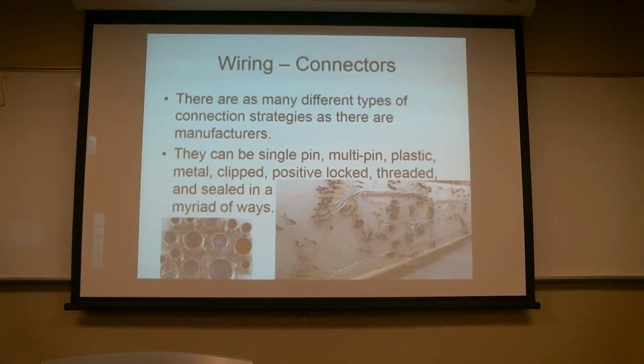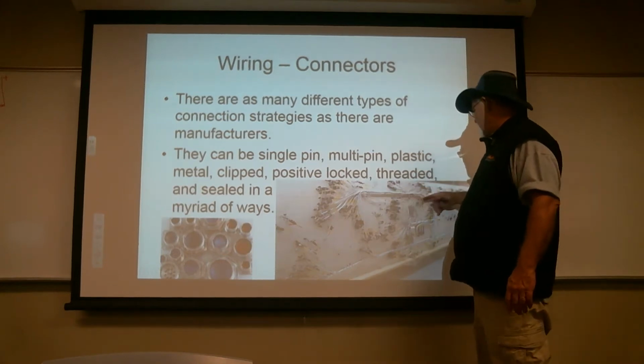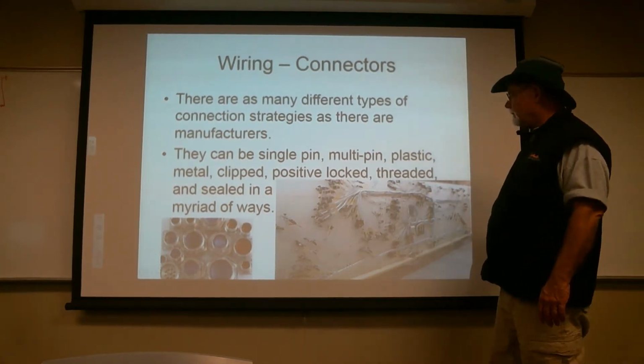We'll then lay that out on a board and somewhat design what the harness needs to look like and where the wires are going to go. Once we do that, we'll go on to a layup board and take all of the vehicle connectors and bolt them in various places so that you get the basic dimensions laid out. You'll then also see a number of pins and other supporting things.